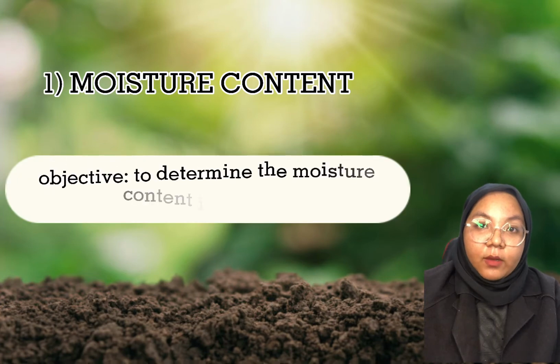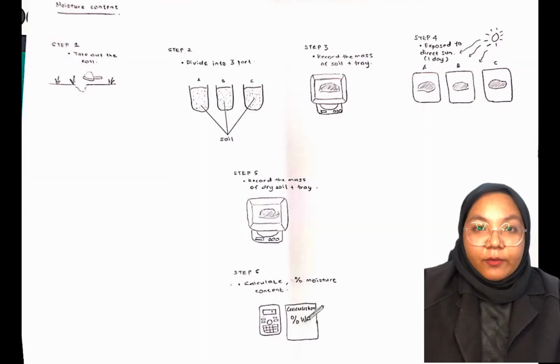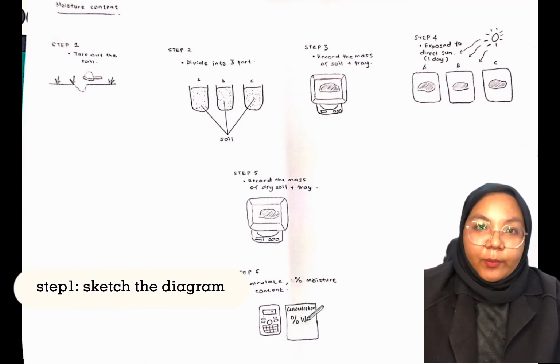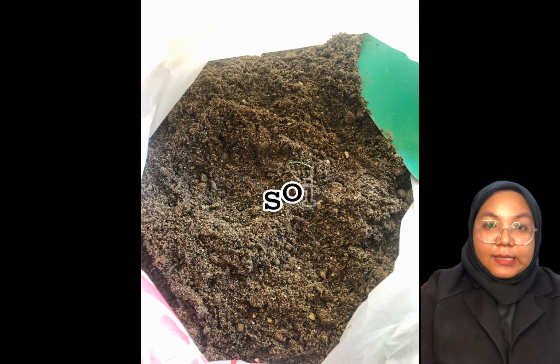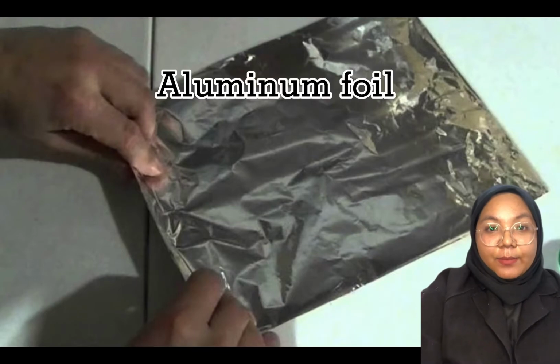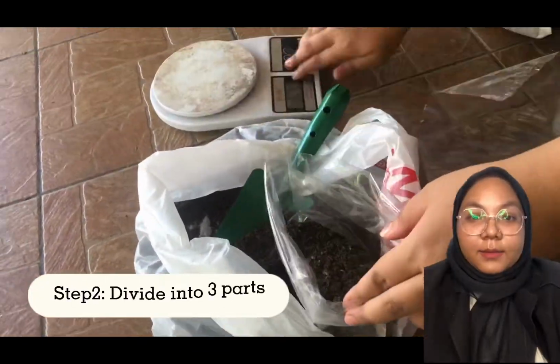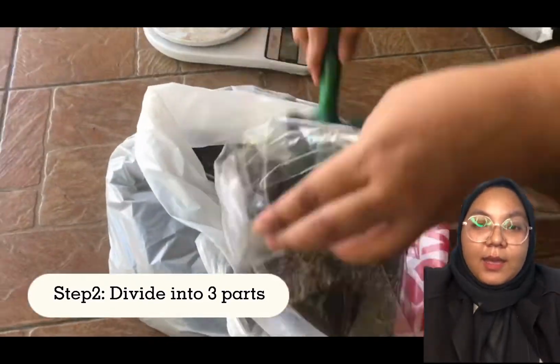The objective of this experiment is to determine the moisture content in the soil. For the first step, I drew a diagram on A4 paper of how I intended to begin the experiment. The apparatus that we use in this experiment are soil, plastic tray, scales, and aluminium foil. Next, we need to divide the soil into 3 parts.